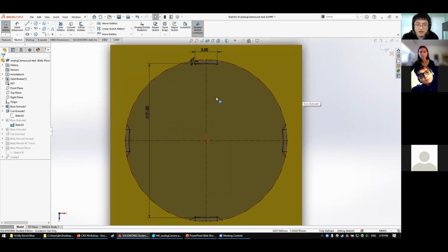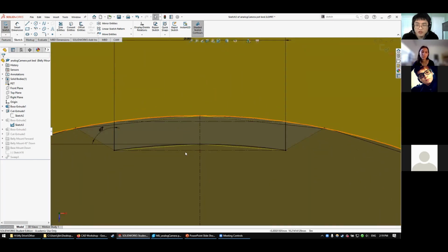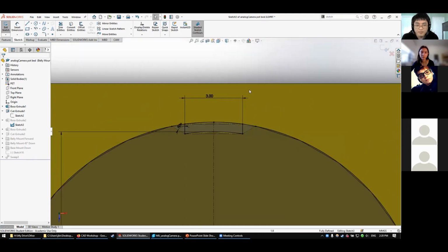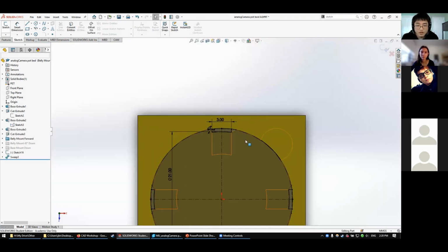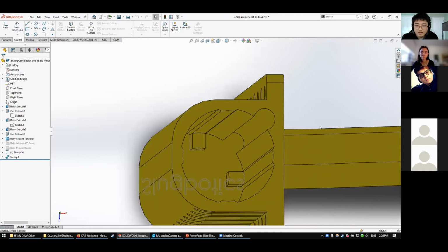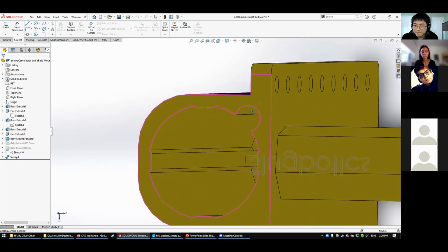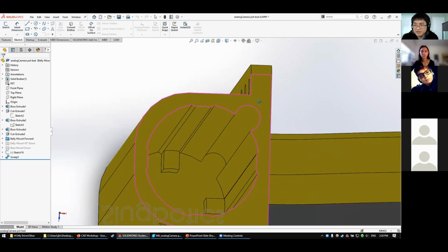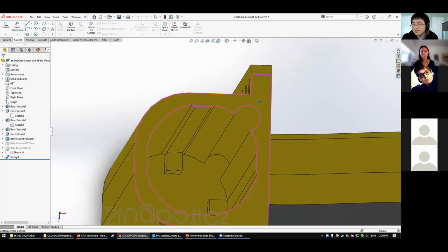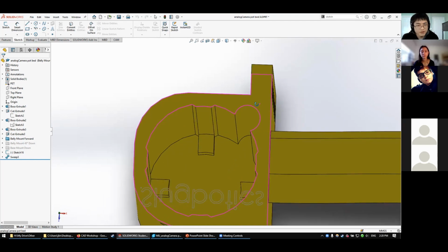So I've used it here. I have here a big circle. I also have a couple small things at the 4 cardinal directions, northeast, southwest. And it's basically a trapezoid with a rounded center. The goal of this design was to hold a camera in it. The camera points outwards, the cable from the back feeds through the small little trough out the front. And then we encase the whole thing in epoxy to make it waterproof while also being able to still see out.